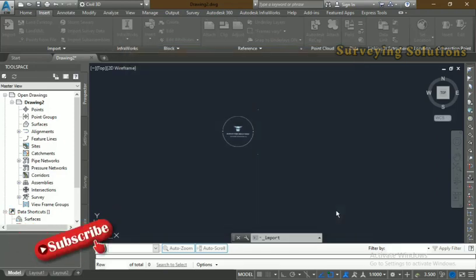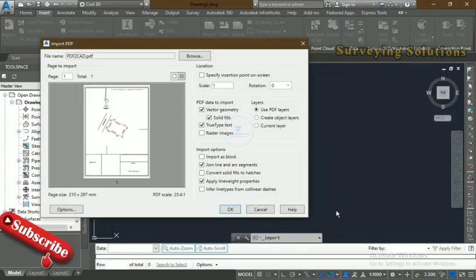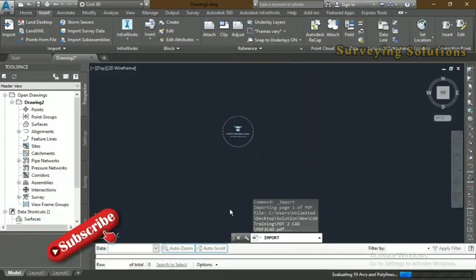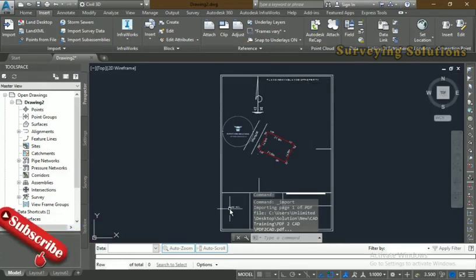Are we together? Good. So this Import PDF box pops up, and I think we aren't going to do much here because we just have one page. If you have more than one page, you are going to select from here the number of pages and the total and the rest of that. The scale is still the same, like it should appear at one scale, rotation 0, as the case may be. So we now move to the page size. I think this should be A4, 210 by 297 millimeters. So we say okay. So this will now import the drawing to AutoCAD.